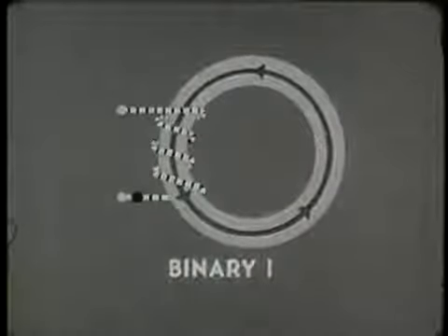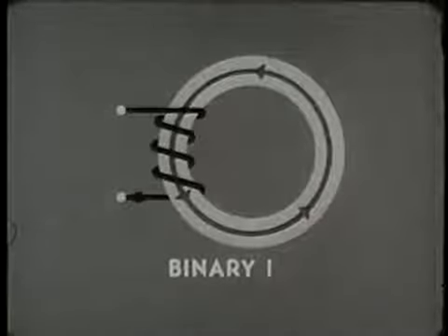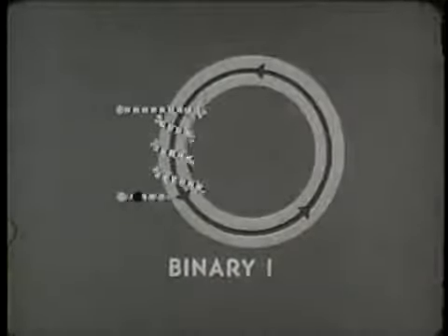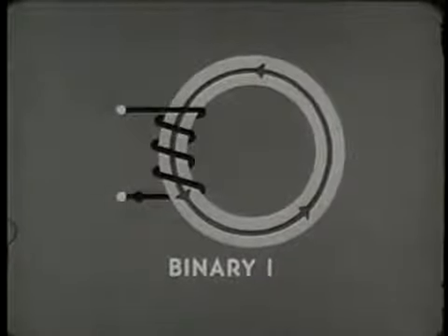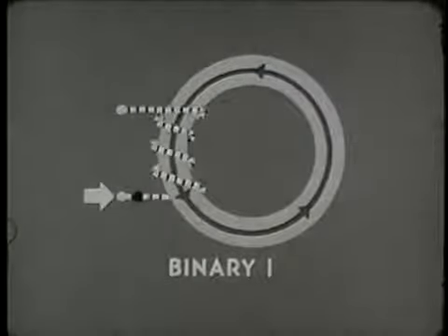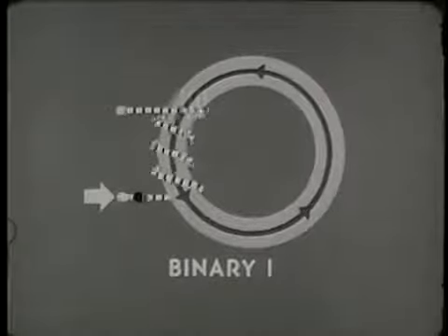When non-dot current sets the core to the binary 1 state, the residual property keeps it that way indefinitely. Suppose there is a second pulse of non-dot current. It will have no practical effect on the core because the core is already saturated with positive magnetism. But if we send current through the other way, into the dot side of the winding, then, of course, the core's state will change.